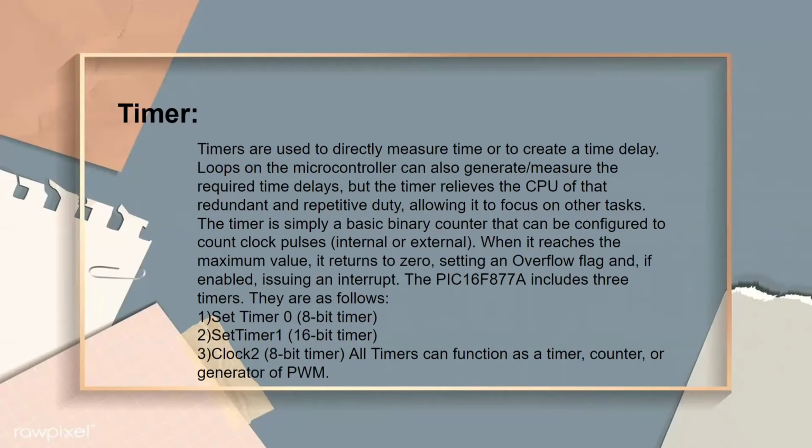PIC16F includes 3 timers. One is Timer 0, an 8-bit timer, Timer 1 is a 16-bit timer, and the third one is Timer 2, which is an 8-bit timer.